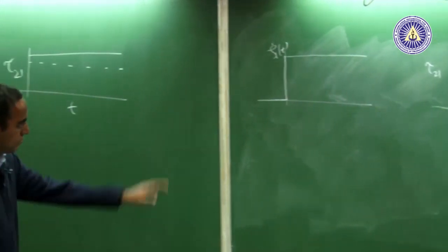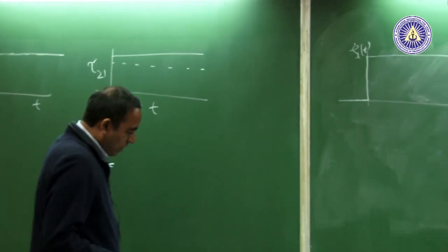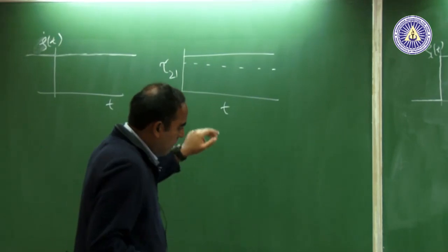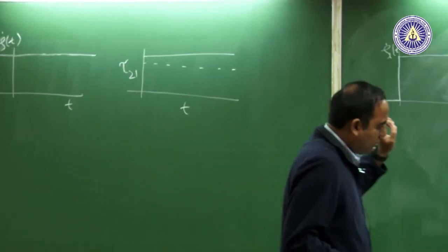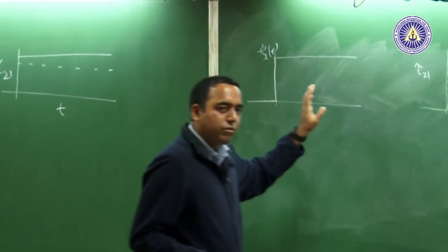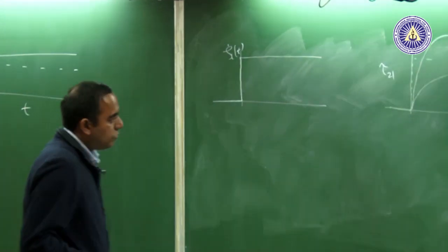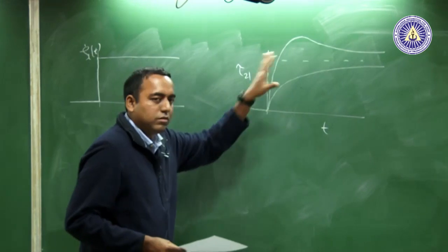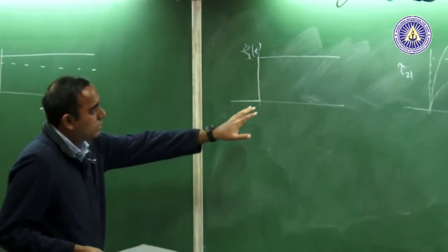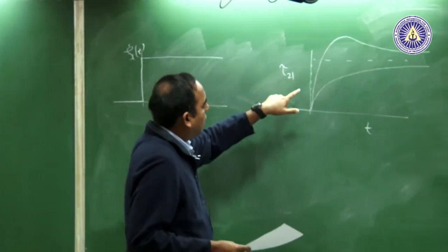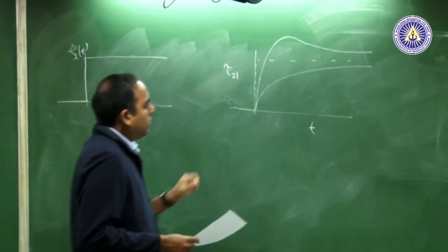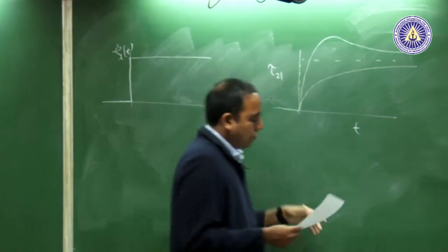Now, this is where the fun begins, in the sense that the first one was steady shear. That is not a big challenge. I will talk about some subtleties about steady shear, but essentially when you are looking at non-Newtonian fluids of the type of polymeric liquids, you should have a model which ideally should capture these sorts of experiments and responses, where sometimes you have an overshoot, and sometimes you have a curve reaching a steady state monotonically.